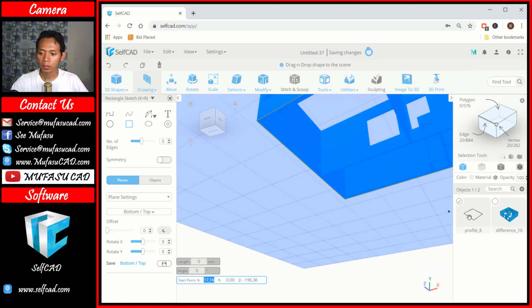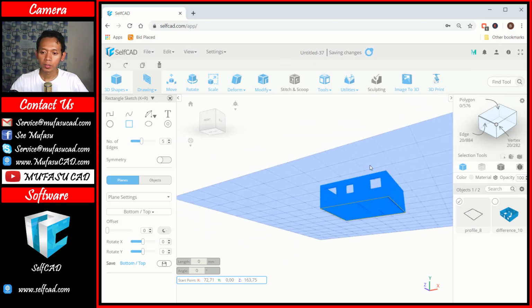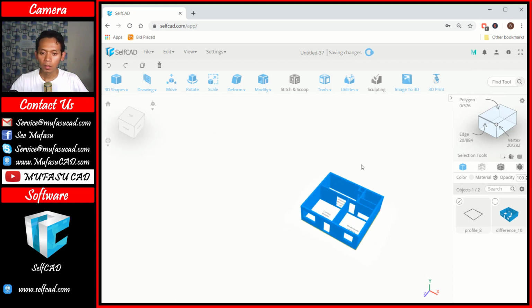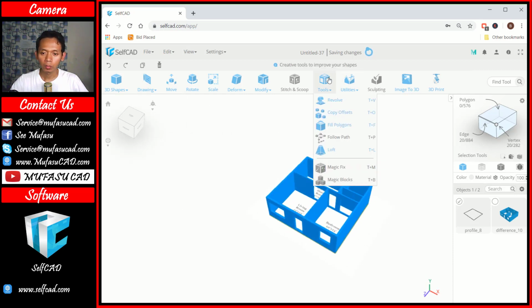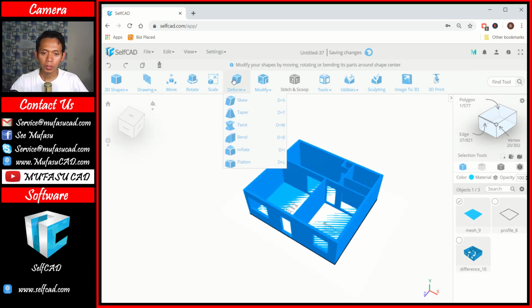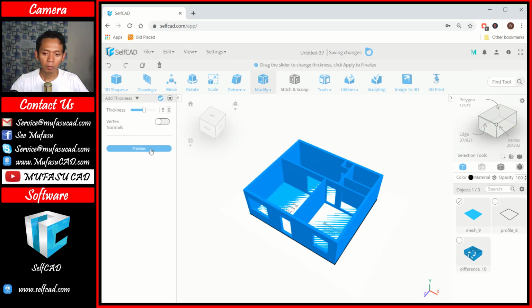Okay, it will create this rectangle object, and then we can use fill polygons. You can close this rectangle sketch. I will use fill polygons. You can click Tools, click Fill Polygons, and then for this surface, I will use a thickness. Okay, we can set thickness to 5. You can preview, and you can click OK to apply.